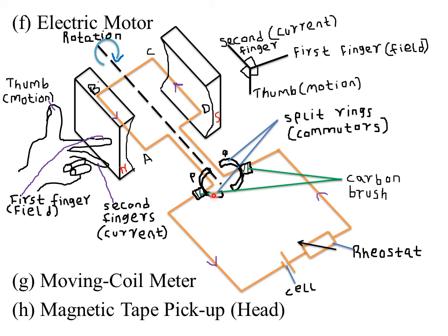So in summary, we've said the four ways through which we can improve the working of the electric DC motor are: one, by winding the coil on the soft iron core; two, by increasing the number of turns of the rotating coil; three, by using a stronger magnet; then lastly, four, by multiplying the number of coils and commutator segments.